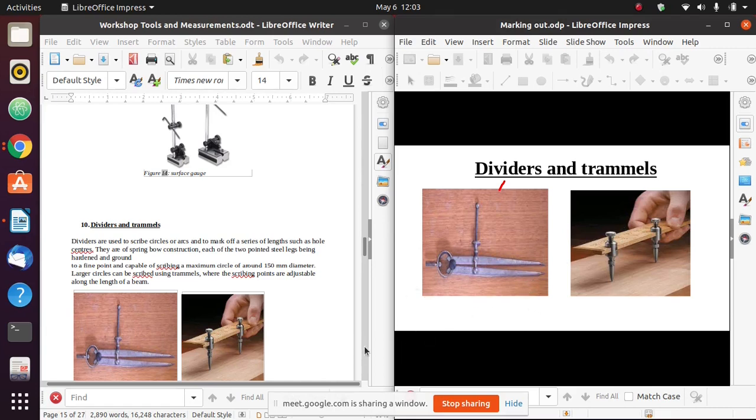accurately on the scale. So I will put these legs, I will open the legs of this divider, place those 2 legs on the 2 points I want to measure, then I can transfer that distance onto the scale so that I can identify the measurement between those 2 points. Then I can also use these to draw lines, to draw circles and arcs.